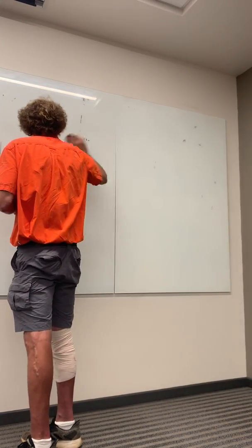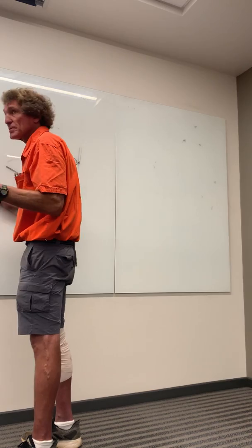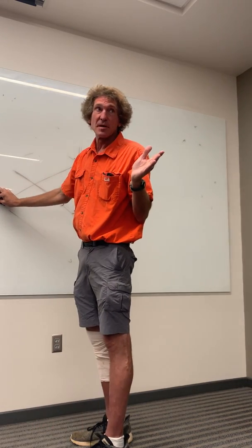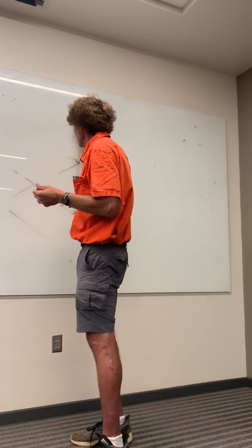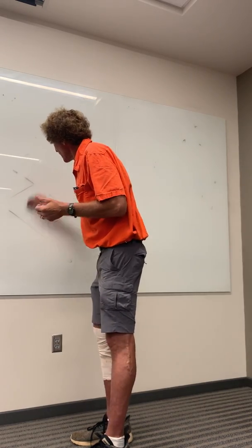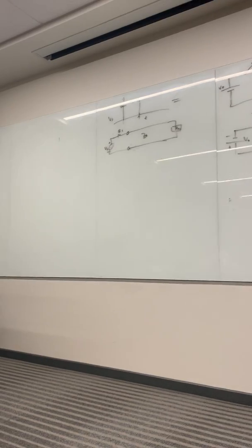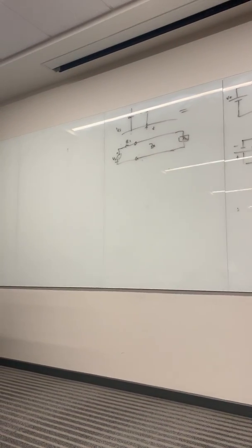And most of the time, on a chip, they're not transmission lines. What they really are, they just look like pieces of wire connecting things. Because they're so short, at the frequency of operation they're much less than a wavelength.